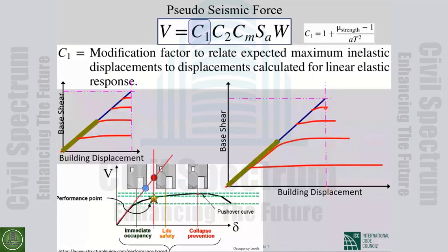But if we do nonlinear analysis, and the strength is less than the applied load and we get damage, the displacement increases relative to the elastic case. And if you reduce the strength, the maximum displacement increases even more. So statistically, this is what they call the equal energy approach: the area under the curve is what is applied.